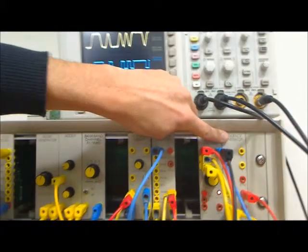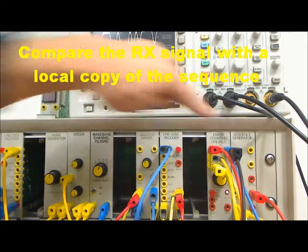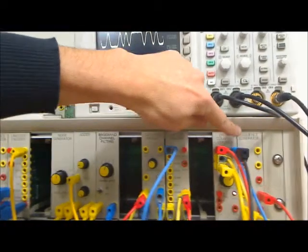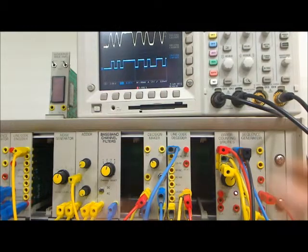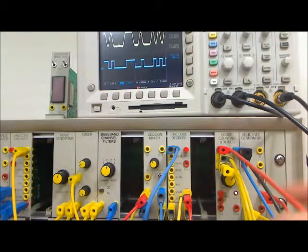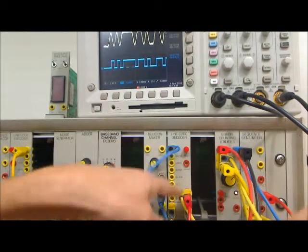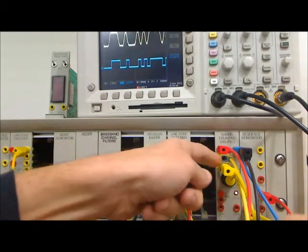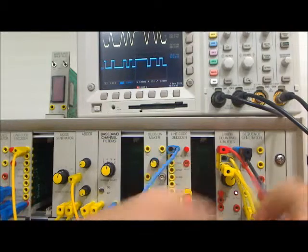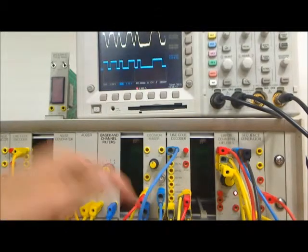You can see here, second sequence generator, which has the same sequence in it as our original sequence generator. We're going to take measurements of the number of errors in the channel due to the noise. So we connect the sequence generator to the error counting utilities. The second input comes from the digital output of the line decoder, and we also need a clock, which acts as a gate. That signal comes from the output clock of the line code decoder.